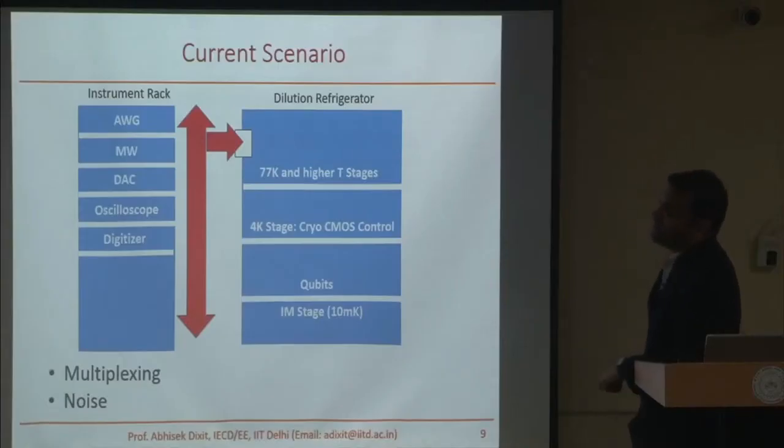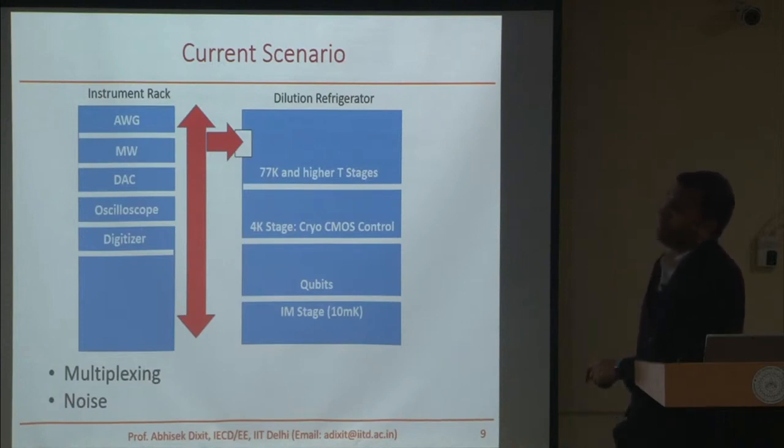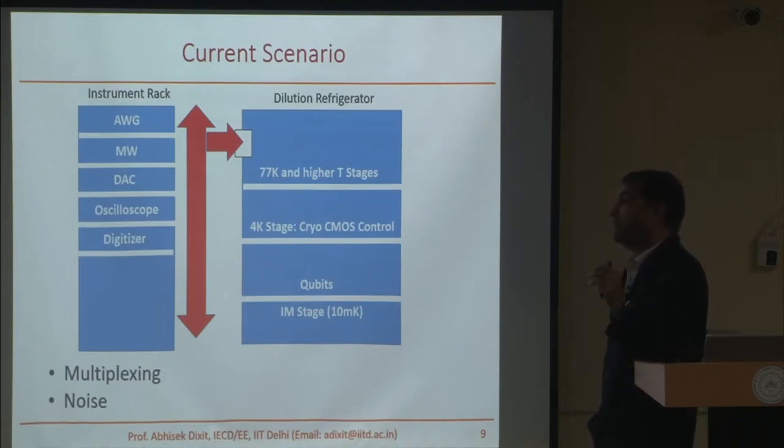Just a couple of days ago, I was reviewing the work of one of my students who is working on low frequency noise. She measured low frequency noise at cryogenic temperature and back calculated the trap density. The oxide trap density is coming out to be 10^13, 10^14, which is something you set at 10^10 at the time of manufacturing. So a lot more traps are getting activated and participating in capture and decapture at cryogenic temperature. This is a new thing we have just now observed.